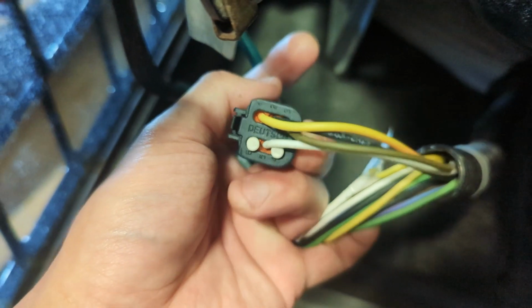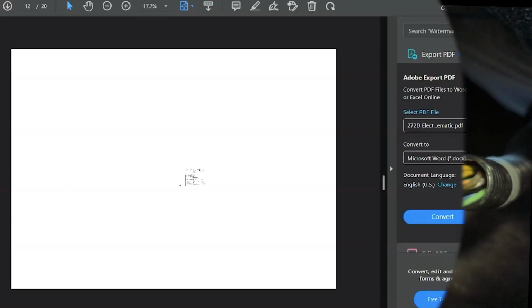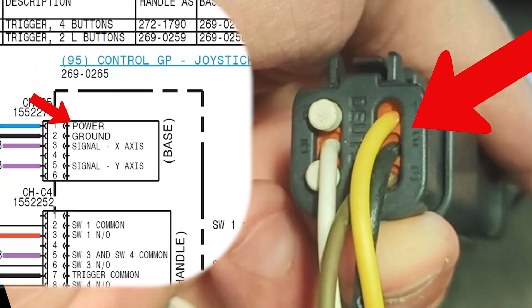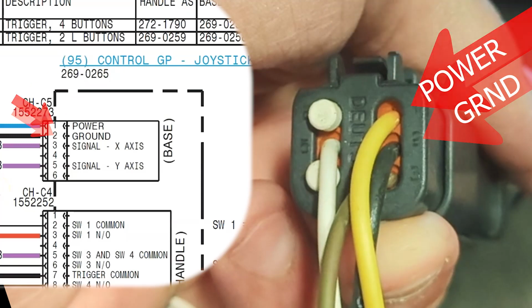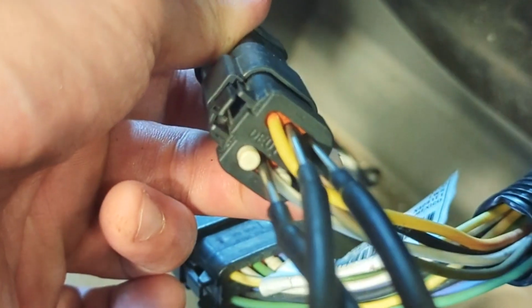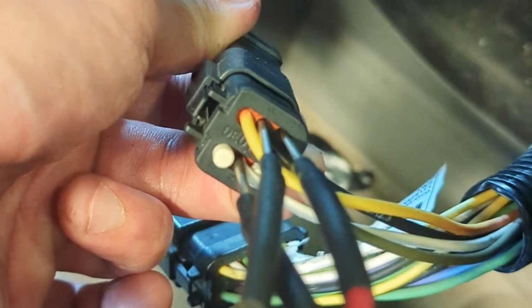The joysticks are typically connected through a harness of some sort. To verify which wires do what, we look at the schematic diagram. This wire is your ground, this is your 12-volt power, and these are your X and Y axis signals. Let's hook up some oscilloscope probes on the signal wires to see what's actually going on.